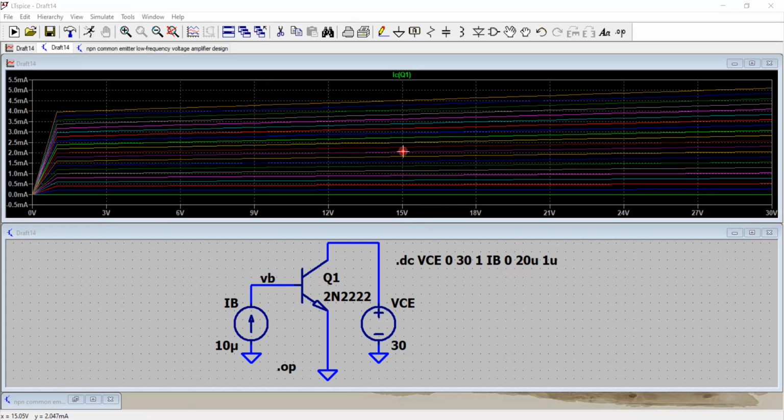Okay, for the supply voltage of 30 volts. So why 15? Because from this midpoint, I can have the output swing up to 30, and from 15 down to 0. So maximum swing, I expect like 30 volts, peak to peak.